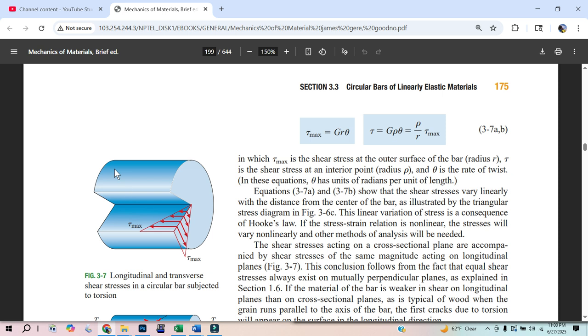Now again, it can be easy to see that if I have two molecules right here, holding maybe compression, and if this one goes that way just a little bit, the distance did not change. But that's where you want to envision four molecules, one right there and one right there. And then when these two molecules go up a little bit, the diagonals do get farther apart, and these diagonals get closer together. So that is the fundamentals of what shear does.